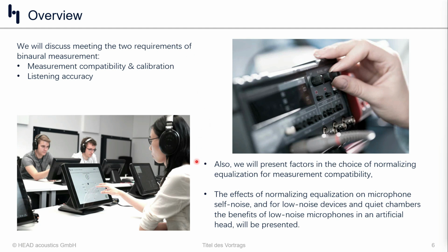You get a wonderful benefit that you effectively have Dolby noise reduction on the microphones, because the dominant factor in the head-related transfer function is a huge resonance of approximately 12 dB amplification of the hollow before the entrance of the ear canal of the human ear. The pinna is a 4 kilohertz amplifier, 12 dB plus. And in order to get that back to a flat response for measurement, you have to reduce by 12 dB. And in the process, you not only reduce the acoustic effect, you also reduce the microphone and the electronic self-noise. So the microphone gets quieter, both objectively, technically, if you will, but also very much perceptually.